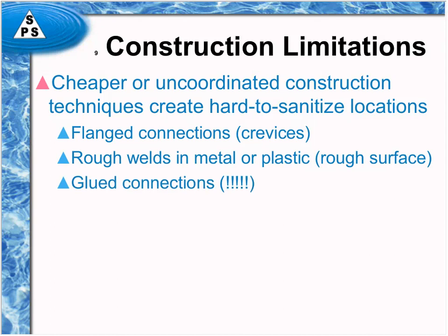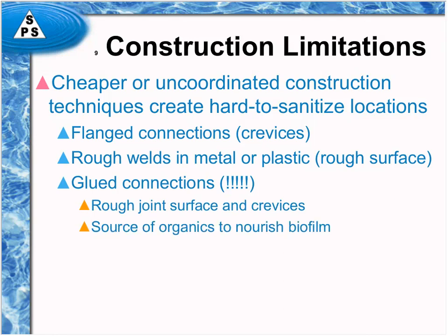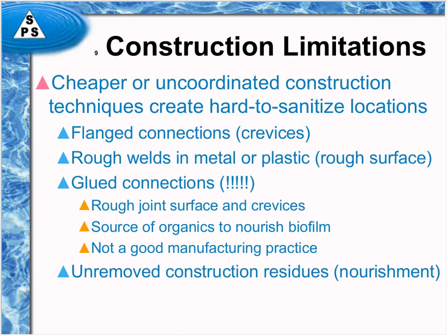Glued connections associated with PVC are just an absolute nightmare because the glue will then slowly leach out into the water and create all manner of food for organisms, and they're very, very rough surfaces when they're glued like that. So PVC is very, very prone to microbial problems. Those organics from the glues and the crevices that they create are just an absolute heaven for biofilm to grow. It's not really good manufacturing process.